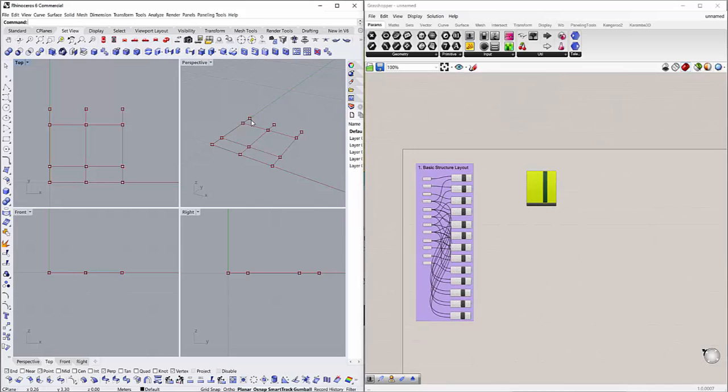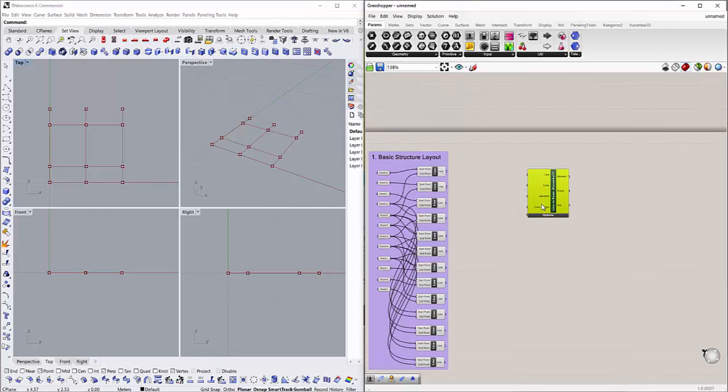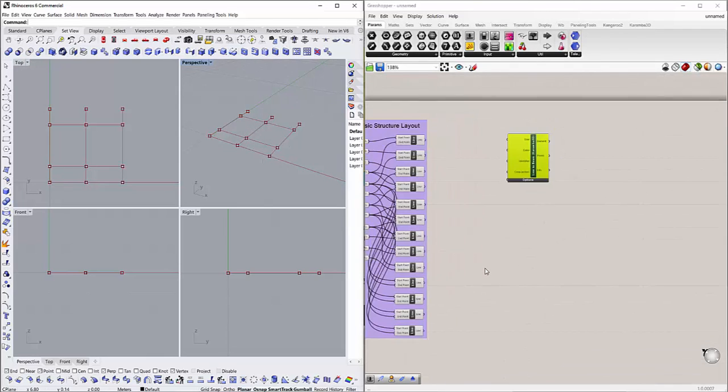So we have 3 vertical mullions and 2 horizontal transoms. So what I would like to do is I'll create 3 different mullion IDs so that I can have every deflection of the mullion separately in my model analysis, and also 2 transom IDs so that I can see 2 different deflections for my transom.